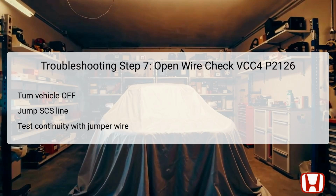The next step involves verifying potential open wires in the VCC4 line, while ensuring all other checks have been completed. Similar to the previous steps, start with the vehicle turned off and then jump the SCS line for a period exceeding 1 minute. Disconnect the PCM connector A, 51P, for complete system isolation. As part of this step, connect the APP sensor's terminal A to body ground with a jumper wire, effectively allowing continuity testing between necessary points.